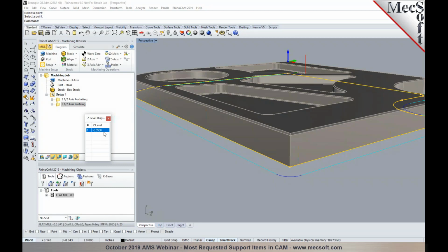and you can see that the Z-level display shows the final depth. The part here in the example shown is 1/2 inch thick, and we specify to go below the bottom of the part by adding in an additional 50 thousandths. So selecting pick top for location of cut geometry will let you cut below or deeper than the thickness of the part to relieve material.